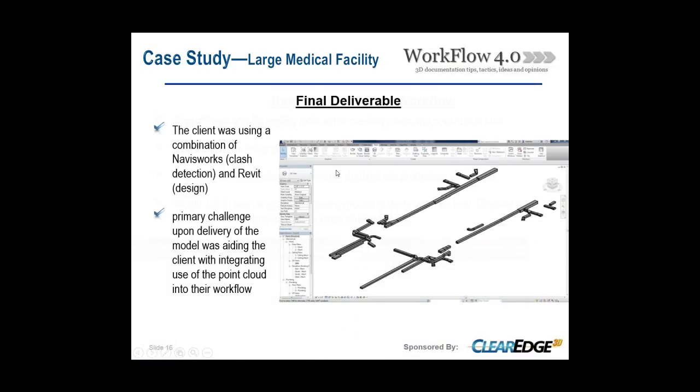All right, thanks, Jerry. Okay, so ultimately, the deliverable that was needed by the client was sort of twofold. They had not dealt with point clouds before, so they had come up with a preliminary design in 3D based on 2D drawings, and we provided a point cloud for them to use within Navisworks to do a clash detection against their preliminary design. Took a lot of coaching. Like I said, it was their first foray, but once everything got running, it was great.